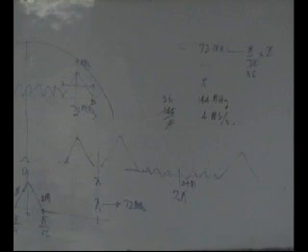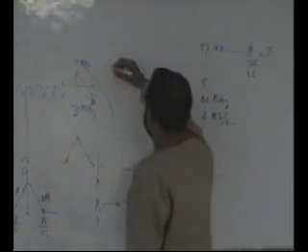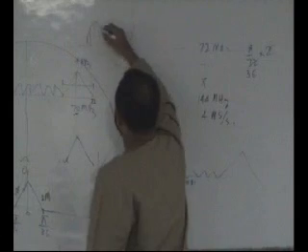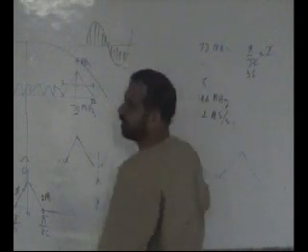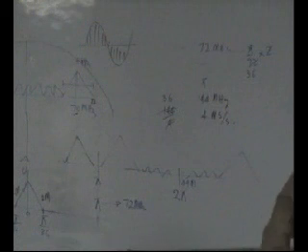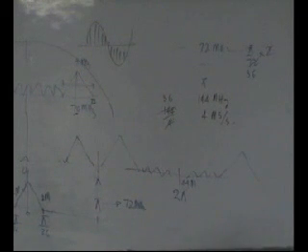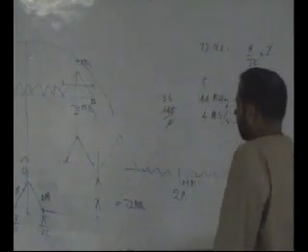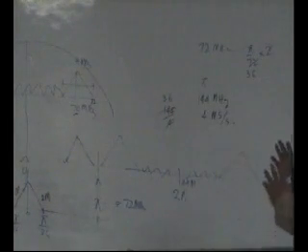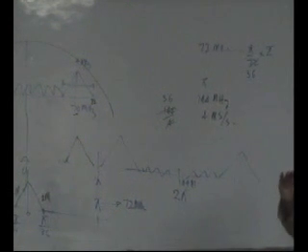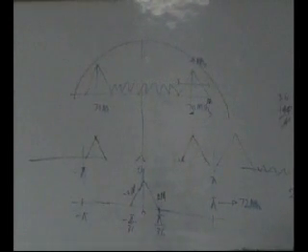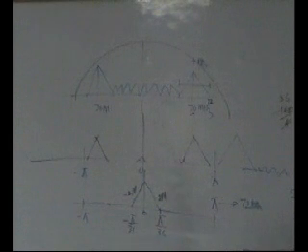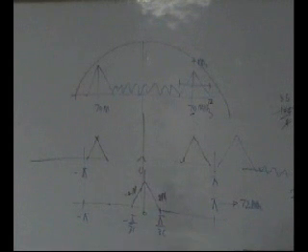These samples are not required because this is equivalent to saying that you have a sinusoid and you have around 70-something samples, whereas you only need 2. So for this reason, whenever in signal processing you are cleaning the spectrum, after cleaning the spectrum or moving the spectrum up and down, after you move the spectrum you have to upsample it, or before you intend to move it up you need to upsample it.